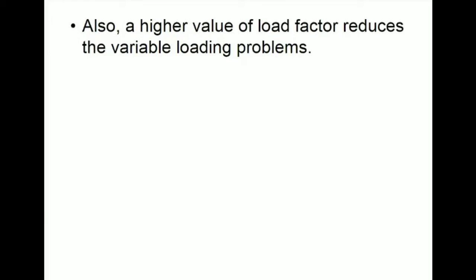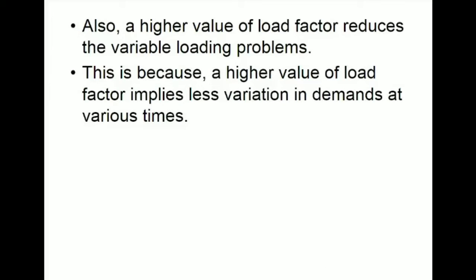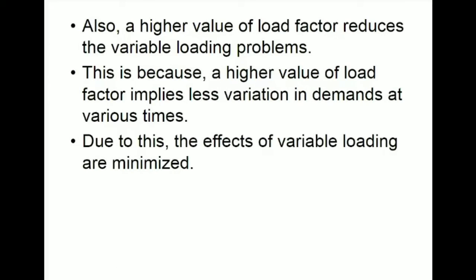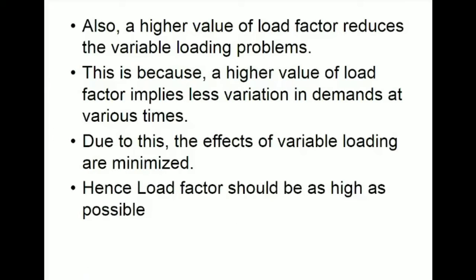Also, a higher value of load factor reduces the variable loading problems. This is because a higher value of load factor implies less variation in demand at various times. Due to this, the effects of variable loading are minimized. Hence, load factor should be as high as possible.